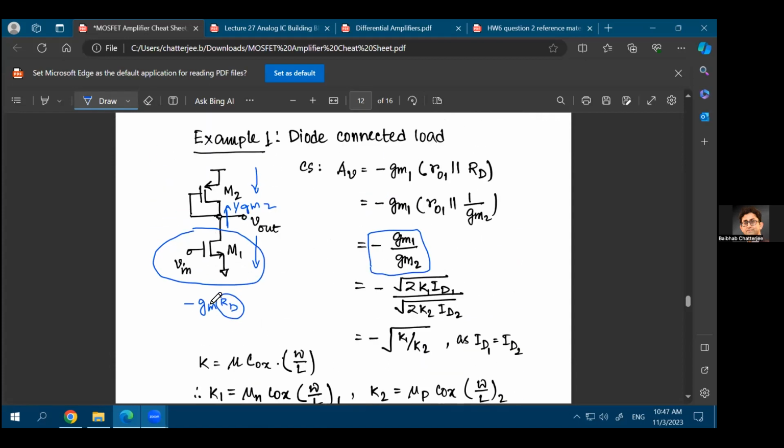But the advantage that it gives you is that you do not need to place a resistor. So how do you actually create a resistance? You will either have to connect an external resistance at this point of the MOSFET, right? So remember that what we had learned earlier, the structure looks something like this, that you are applying your input at the gate over here, and this is your RD resistance. So this RD resistance could be something that is external. So you have a MOSFET which is micrometers in width and length, but then outside you have a resistance that is a few centimeters in length and width and so on. That is one possibility, and that works.